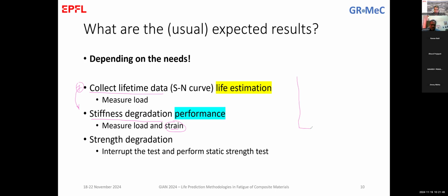Okay, so you have the specimen on the machine. You can put strain gauges, fixed here and there, and loaded. Yes, so then this strain gauge gives you the strain at that point, which is the point of interest, because we know that close to the grips we have stress concentrations. So we need to go to an area away from the grips and we measure the strain. So you can put strain gauges. You can also, so method one, method two, DIC, digital image correlation, that gives you the full field measurement of the area.